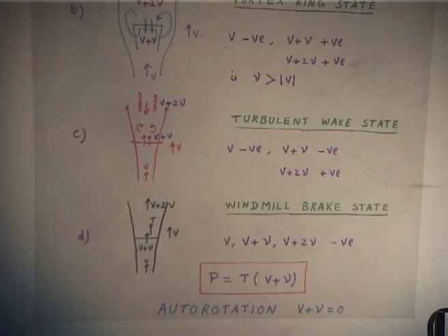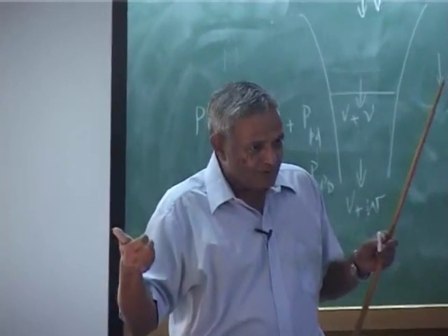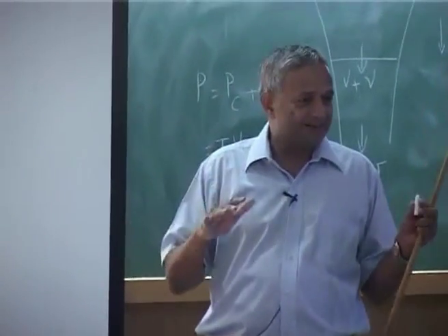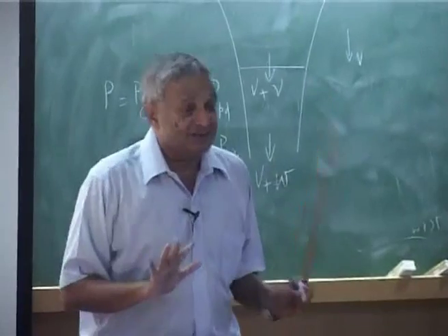Suppose you start descending faster than that condition, what you are doing is you are generating power. When you start generating, that means the rotor will start going faster. But in the design of your blade, there is a limit, you will have a centrifugal force which acts at a particular RPM. I told you right at the beginning, in helicopters your rotor omega is a constant.